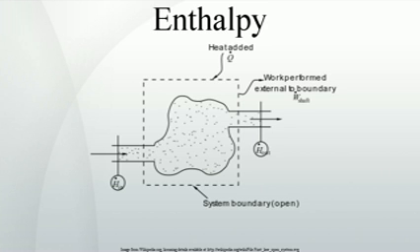One of the most common diagrams is the temperature entropy diagram, TS diagram. An example is Fig 2, which is the TS diagram of nitrogen. It gives the melting curve and saturated liquid and vapor values together with isobars and isenthalps. These diagrams are powerful tools in the hands of the thermal engineer. Some basic applications. The points through H in Fig 2 play a role in the discussion in this section.